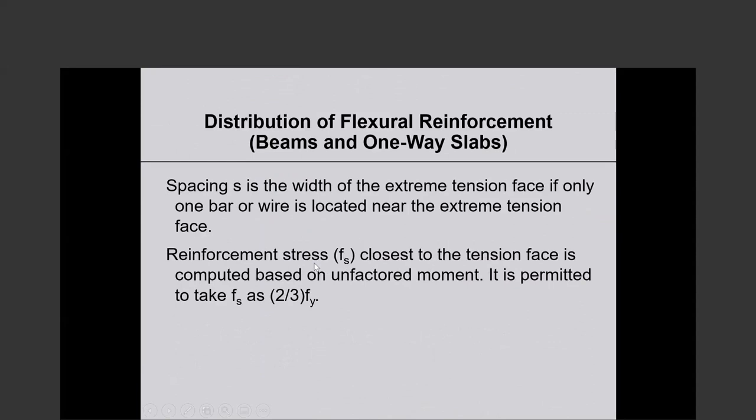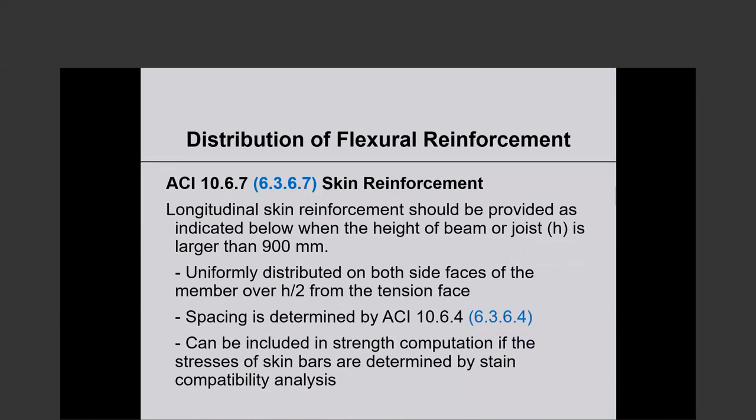Now, this is important. Reinforcement stress F sub S, closest to the tension face, is computed based on unfactored moment. As I said, service level loads. Unfactored moment is a better description. It is permitted to be taken as two-thirds of F sub Y. And that's what we almost always do. We don't try to calculate F sub S. Two-thirds of F sub Y. Okay, so that's crack control.